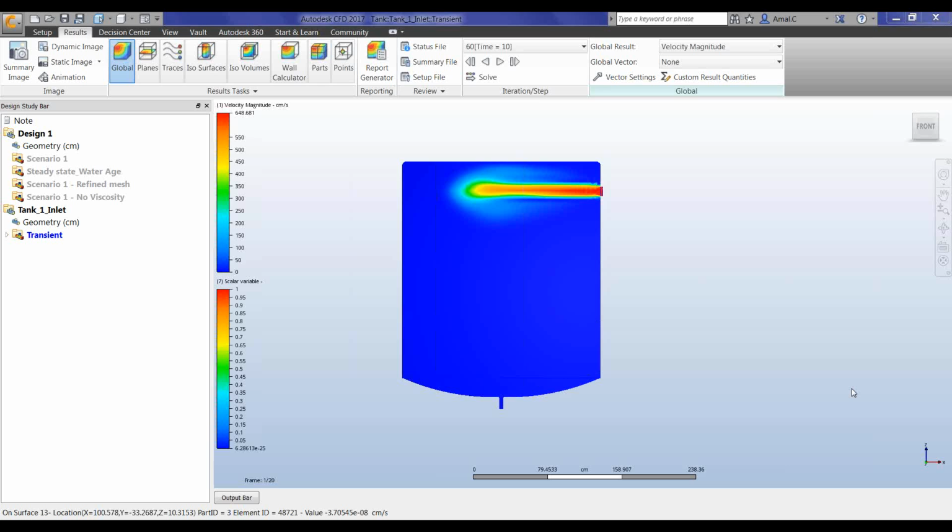I think it's important to define it when you're studying heat transfer. But for only the fluid flow, or the mixing flow, you don't need to define gravity. That's right. It doesn't give you that option, actually, unless you click on heat transfer, and that's when you get the gravity. So it's not important to define gravity as long as you're studying the fluid flow, not heat transfer.